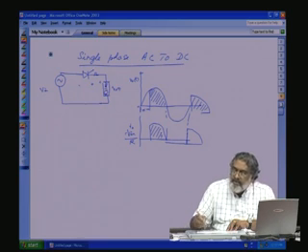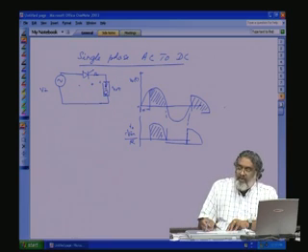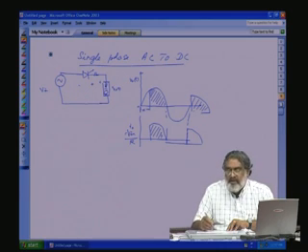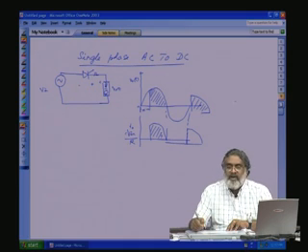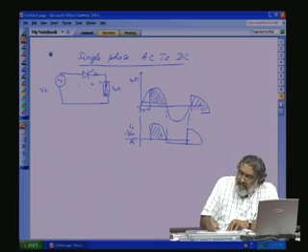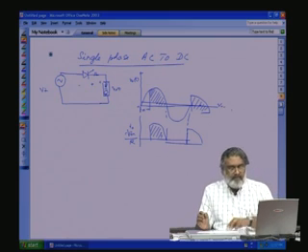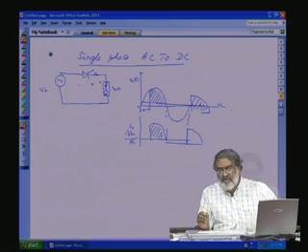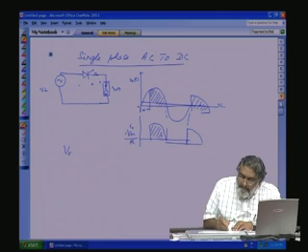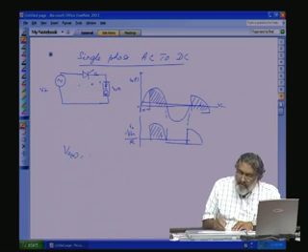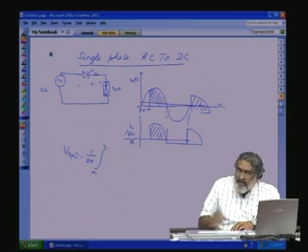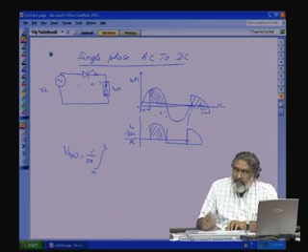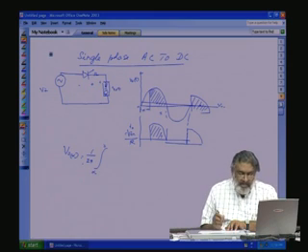So, we will see a pulsed waveform coming across the load. In this pulsed waveform, it will have the DC value and the high frequency AC value also will be there. We are worried more about the DC value. So, what is the DC value? That is V0, the average value of this pulsed waveform. That can be easily found out. V0 alpha will be 1 by 2 pi, that is the average value, integrating from alpha to pi. This is our pi. So, we integrate from alpha to pi and divide by the period, and you will get the average value.